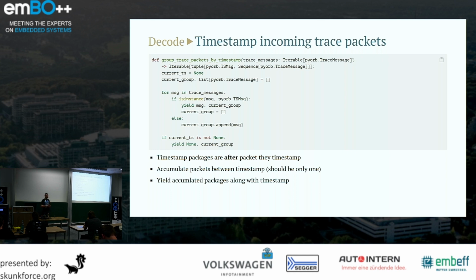If our connection to the target is good, then it should be one data packet, one timestamp packet. I never encountered a problem when I got more than one data packet per timestamp, but that's because I was using the parallel trace probe. So that was not an issue for me. If we lose some timestamps, then we need to recover something or just treat it like a bit later event or previous event. We already got a bit of garbage data at that moment.